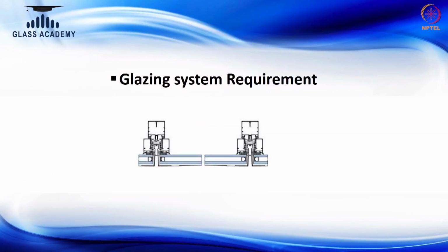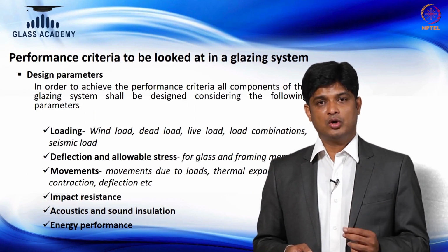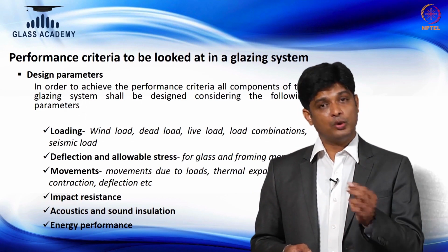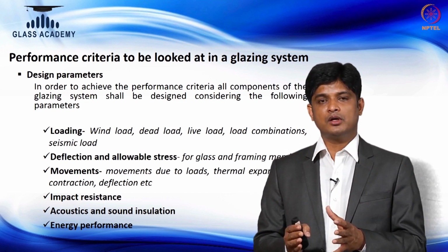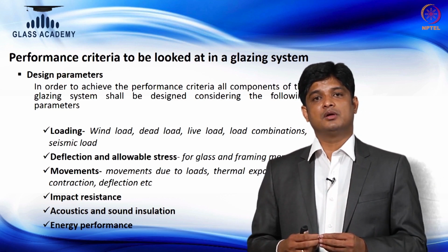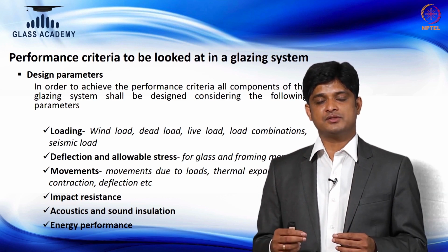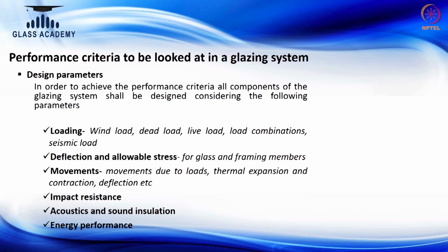So just to have a small brief, we have gone through the glass. Similar to fire, where systems are important, with respect to glazing also the systems are very important, because they have to go through different kinds of tests and design requirements. It starts from the loading condition the frames are designed for: wind load, earthquake, panel dead load and live load. All this has to be considered during the design phase to define the cross section of your members.